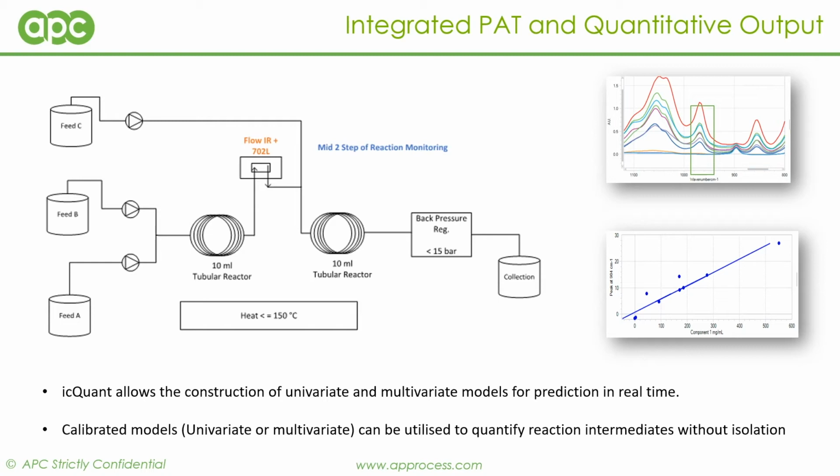Using feedback control, we were able to optimize the concentration of the product in the output liquors and minimize the remaining starting material. Through automation, we were able to do this throughout the lab day unsupervised, but also to carry out some experimentation overnight.